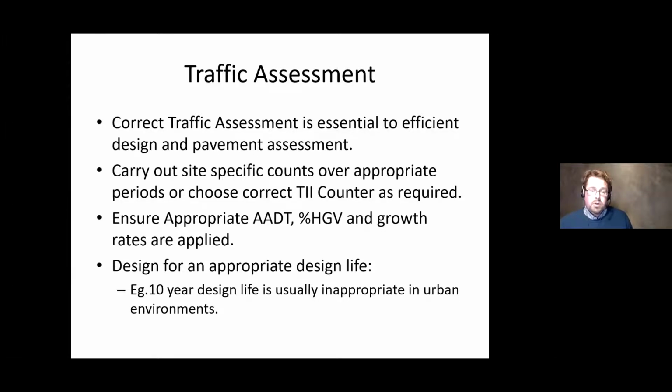Industry seems to be working, but our commuter traffic is down. Like cars, I know I just said they're spacing, but they do contribute. But just try and get appropriate periods to carry out your count over, and for a national road it shouldn't be less than 3 weeks. But to be fair, most national roads, thankfully, the TII have an excellent series of traffic counters across the country.